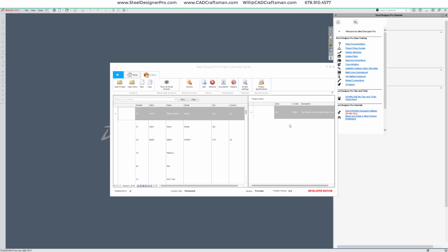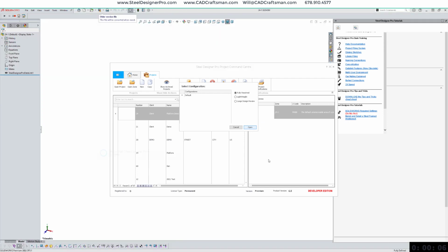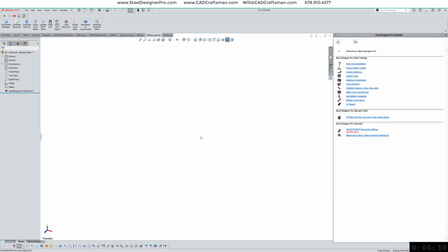Configurations are listed to allow opening the assembly in a working or all suppressed configuration for speed. While populating the model, it is best to check the box for Disable Consolidation to pause the process until we are ready.